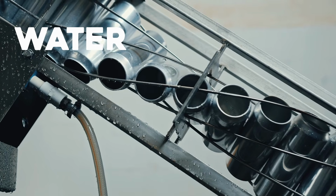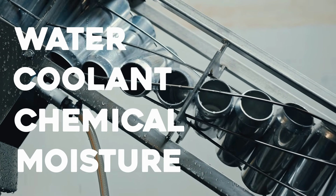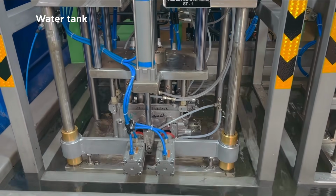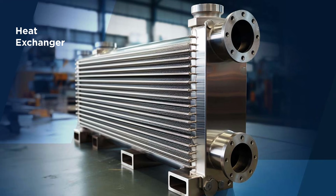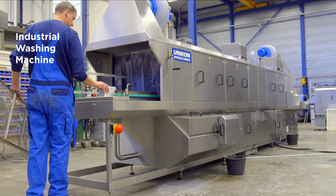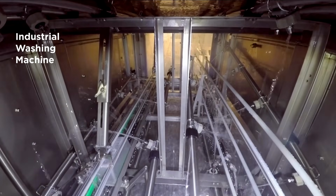In machine design, these grades are commonly used in applications where we deal with water, coolant, chemicals or moisture, mainly to resist corrosion. For example, water tanks, chemical tanks, piping, heat exchangers. In marine equipment, even complete industrial washing machines are mostly made of stainless steel. We also design fixtures in stainless steel.